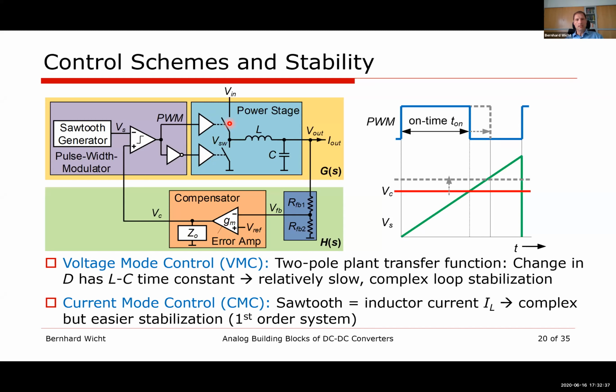What else can we do? Yes, there are some concepts called resonant conversion. They do not apply hard switching, rectangular control. They let this LC ring so that we have a resonant behavior. And so instead of rectangular noise contributions, we have mainly sinusoidal waveforms. And that also really helps in the EMC spectrum. Yes, it doesn't solve it. I mean, there's always EMC. That's for sure. Yeah, many thanks.